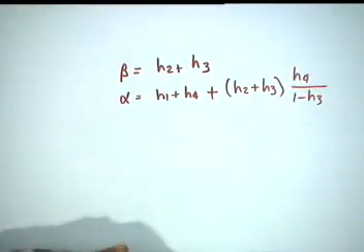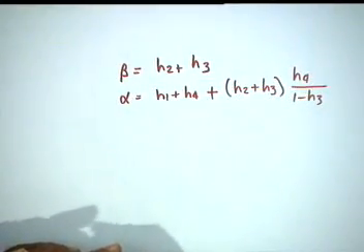But that may be compensated by the reduced number of multipliers in the linear phase term. Do you understand? You see, if it is general H5 plus H5 z to the minus 5 or minus H5, you make that H5 1 and bring it out so that the transfer function remains intact.